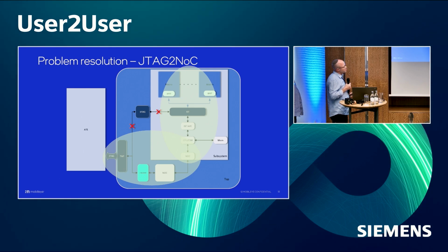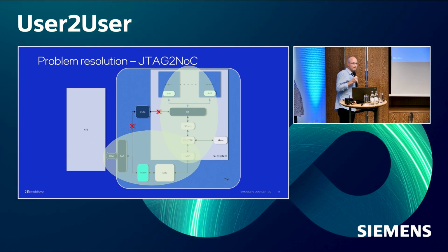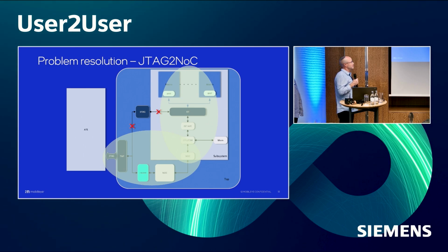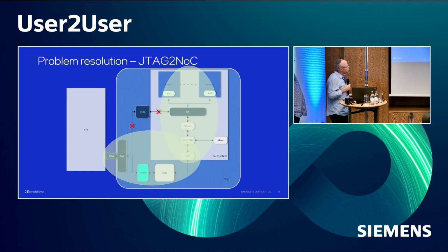From there on, once I initiate the test, I test the device with the actual real functional logic, with all the functional clocking, with all my real clocking and synchronization schemes and the real custom interfaces. In this manner, I provide the missing production coverage for all our custom logic. So, in terms of problem resolution, we enhance the coverage and use our proprietary logic to exercise the real data path with all its complexity.